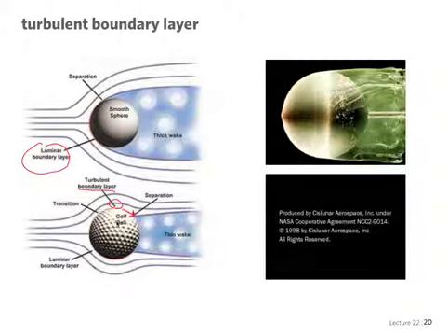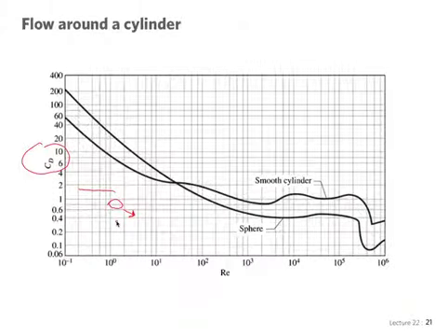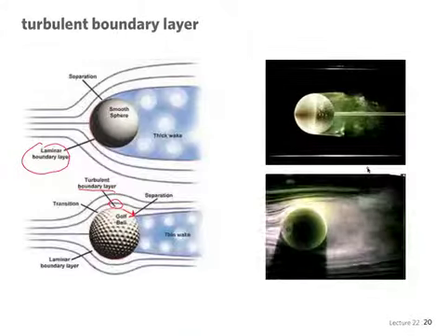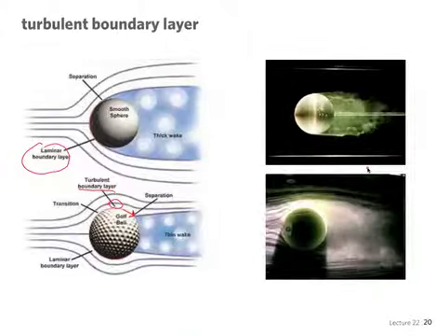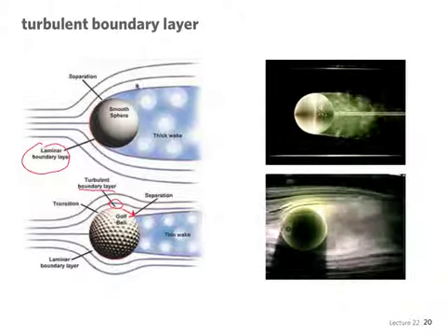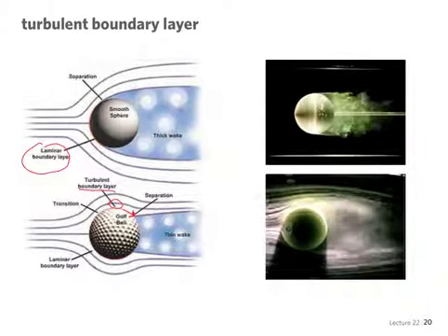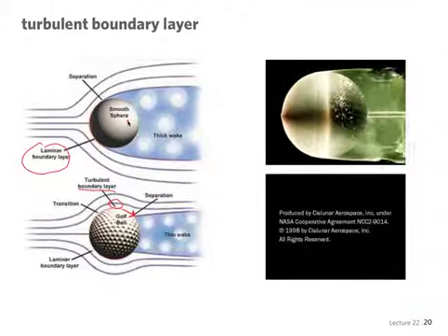Yes? So is this specific to the sphere, or does this work for other shapes? This is specific to the sphere. The cylinder experiences something similar, but not quite as much. But it's very dramatic for the case of the sphere. So an airfoil is not a bluff body, and you don't have the wake. If you did, it wouldn't generate lift. And so it doesn't experience this effect at all.